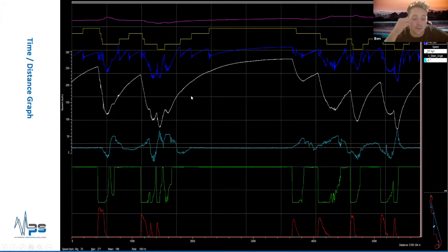Most of them default to what's called auto scale. So it'll go through the data, find the maximum value and the minimum value, and set the display up according to that. Not really an issue in isolation on a single lap, but if you were trying to back-to-back compare 2 drivers, obviously there could be significant differences here. So what I tend to do is fix the range in which I view the data myself, so each time you load it up, you know where you are with it, and you're not constantly adjusting your scale to suit the particular data you're looking at.